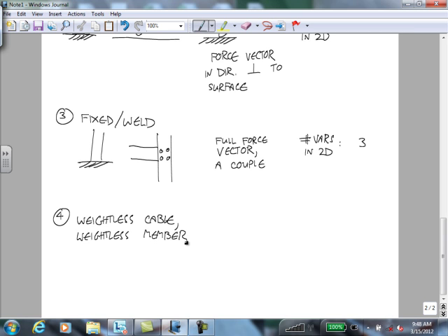There are a couple of cases where, for example, think of a contact with friction as opposed to a pin joint. Think of a contact without friction as opposed to a pin in a slot. And also think of these two in relation. They're treated the same mathematically, but one of these types restricts more motion than the other type, right? Like this member is free to hop up into the air, right? This one isn't. If this was connected by a pin to the floor, it wouldn't be free to hop up into the air. So what does that mean for how they're treated mathematically?